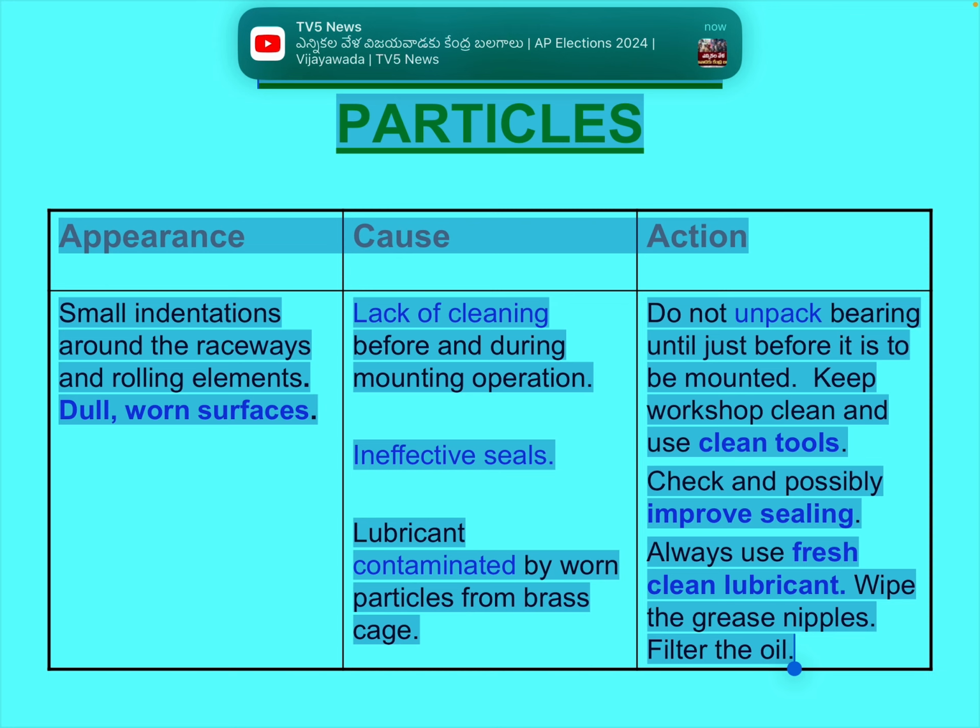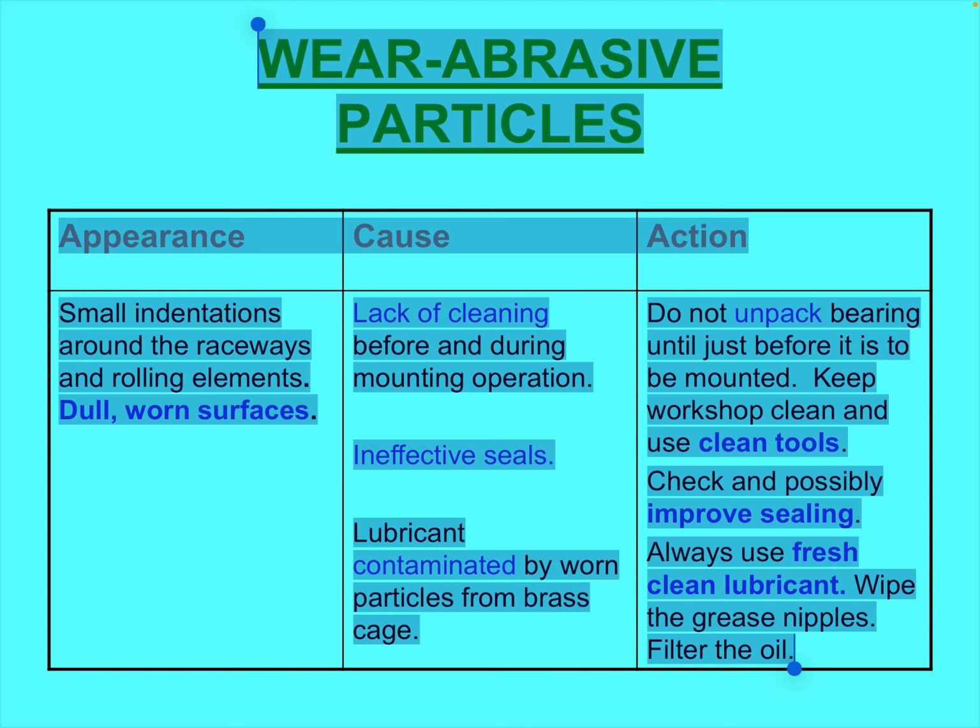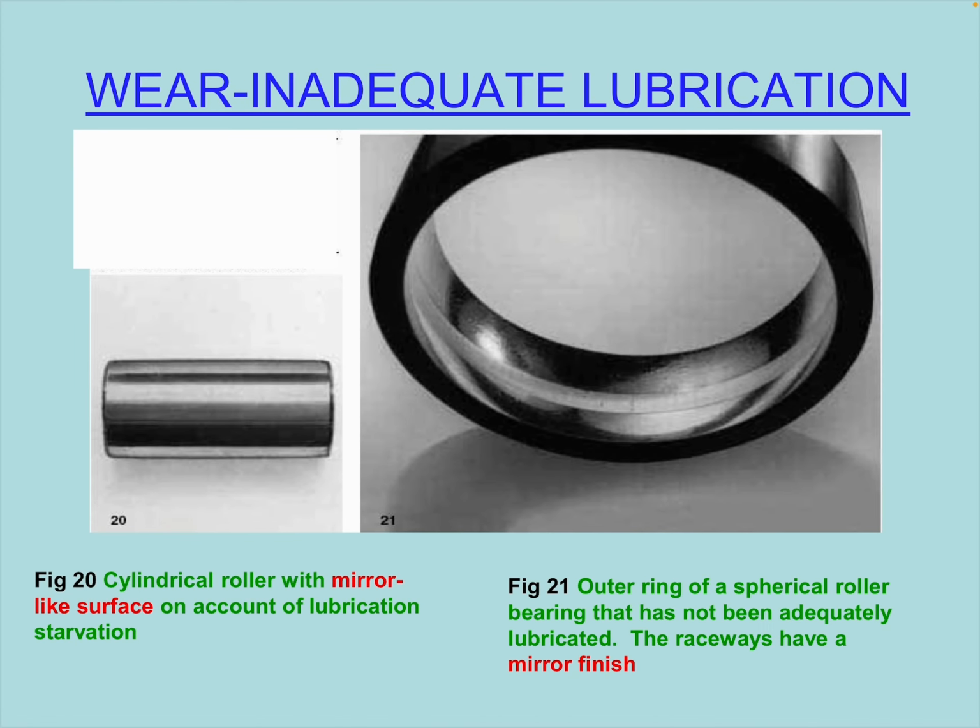Action: do not unpack the bearing until just before it is to be mounted. Keep the workshop clean and use clean tools. Check and possibly improve sealing. Always use fresh clean lubricant. Wipe the grease nipples. Filter the oil.